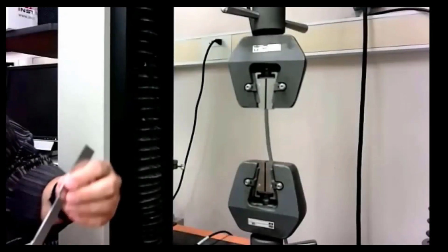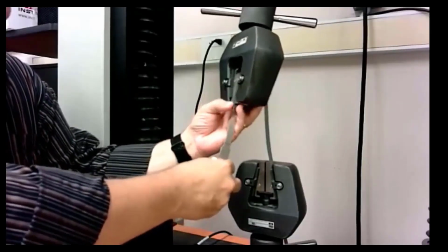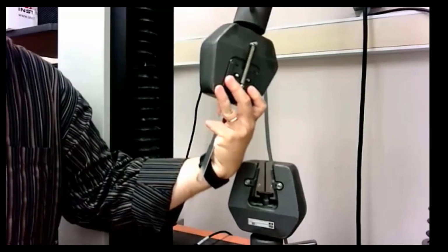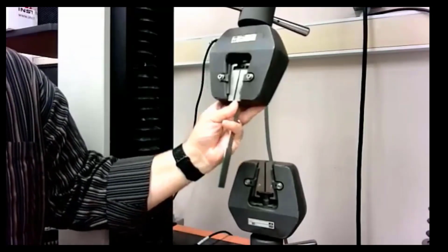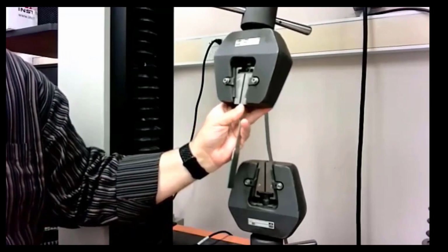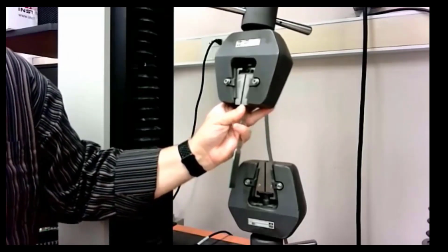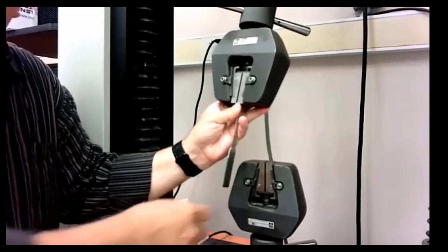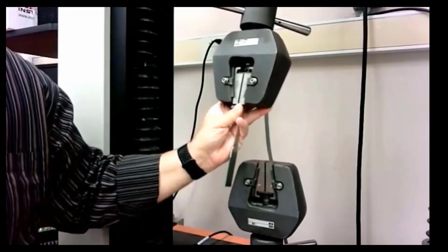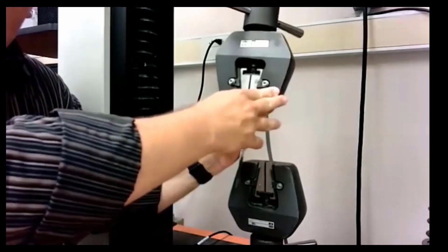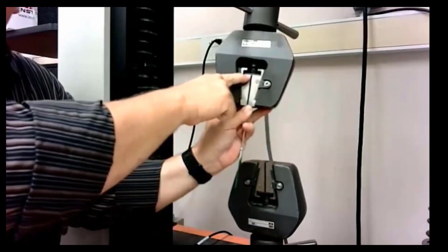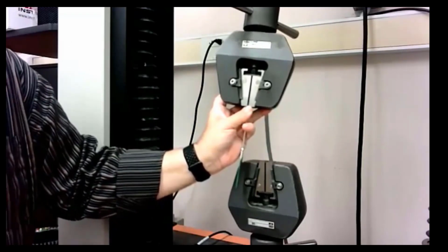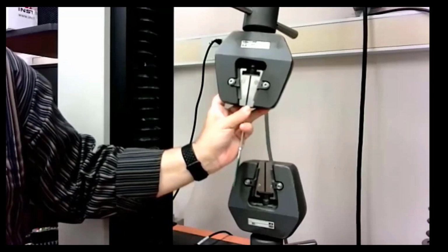To do this, I'm going to take my specimen, slip it in place, and hold it with my thumb. You can see that I've wrapped my fingers around the back of the jaw, and now use my thumb to hold the specimen in place and my pinky finger to prevent me from tipping it backwards. But now I can feel whether or not the specimen is flush against that backing plate. I also want to make sure that I have about 1/4 inch gap at the top so that the specimen is not forced up against the plate that is moved by the screw to actually tighten the jaw.